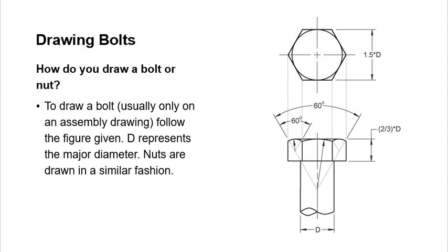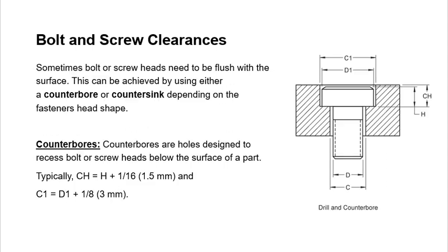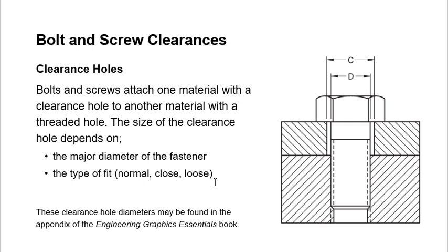So anyways, let's go down to clearance holes. Clearance holes are very important, by the way, for fit purposes. In the real world, we have 2 parts, because we usually fasten by using bolts, and the clearance holes join the 2 parts in mating. The clearance hole is going to allow this bolt to be attached to this material, to that material. We know that you're dealing with 2 parts because of the cross sections right there, the section view.